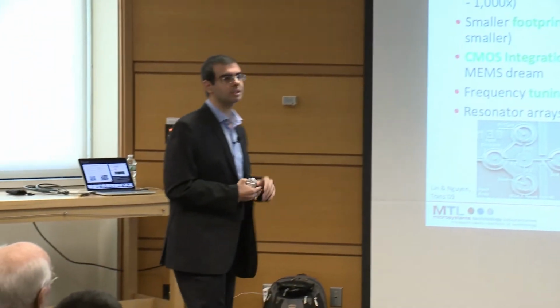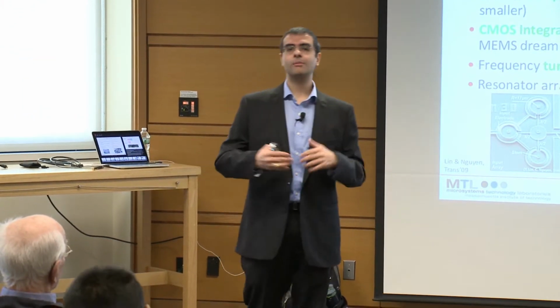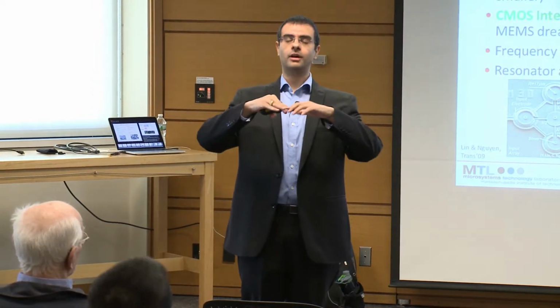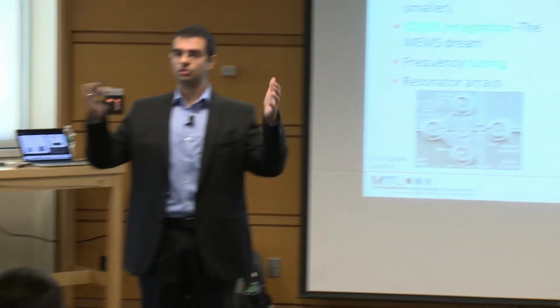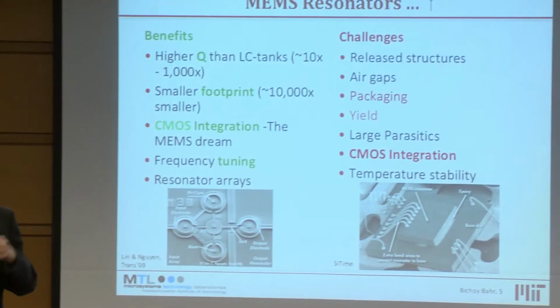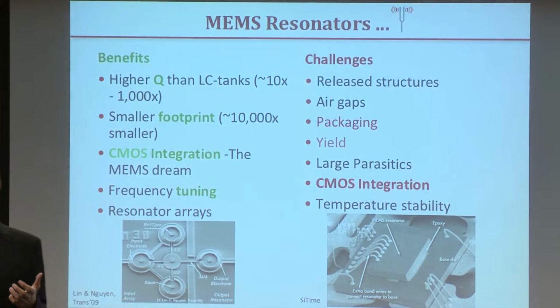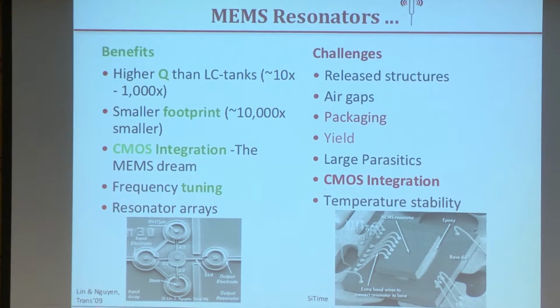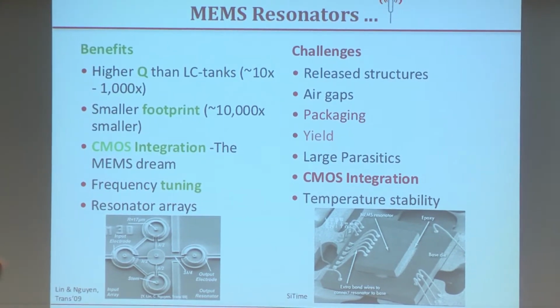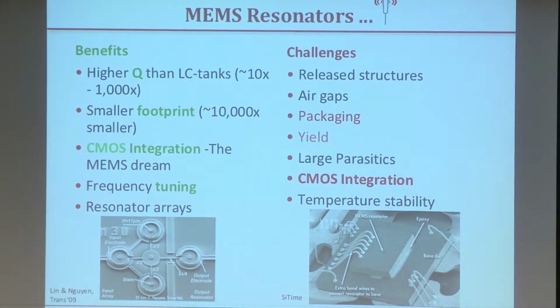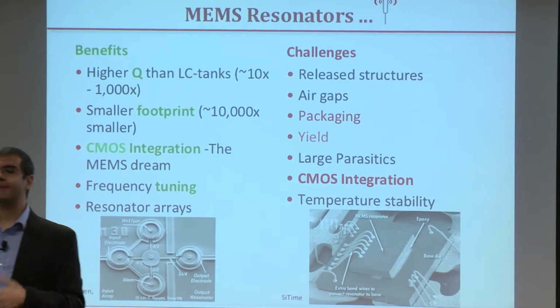But they also come with their challenges. MEMS resonators that mechanically vibrate need to have free surfaces in order to vibrate and move. And once we start talking about free surfaces, we start getting into trouble. Why? Because our device will be highly sensitive to the environment. It will probably be affected by pressure, by humidity adsorption, and by particle deposition. All of that leads to packaging challenges.